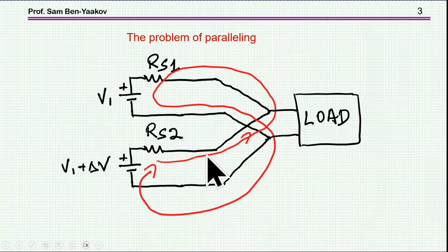Now, if you just connect two power supplies in parallel, having a low output impedance or resistance, because this is a voltage source, and since the output voltage of a power supply is not an exact value, there is a spread here, and also it's temperature dependent, then if you connect two power supplies, chances are there's going to be a very heavy circulating current because one of the power supplies will have a higher voltage, and this will induce a short circuit as a matter of fact between the power supplies.